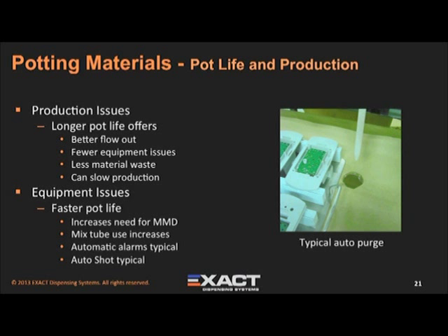The shorter the pot life, the more likely your equipment solution will require an AutoShot Pot Life feature. The picture you see on this slide shows a hole in the production table that will hold the automatic dispense valve, so when the Pot Life AutoShot goes off, the material is purged into a waste container and not onto the floor.